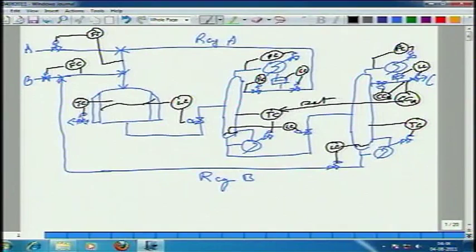Yes or no? Okay. Now, since degrees of freedom 2 each for the 2 columns, that is 4, 2 for the 2 fresh feeds makes 6, plus 2 for the reactor temperature and level, or temperature and hold up. So, that is 8 degrees of freedom. What are the 8 things that the operator is setting?